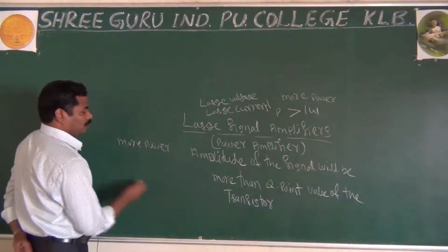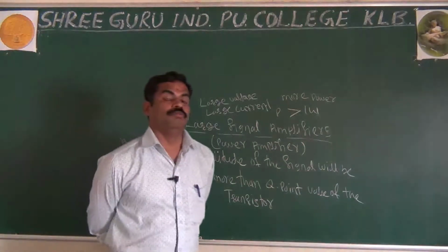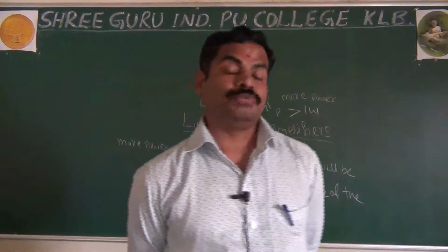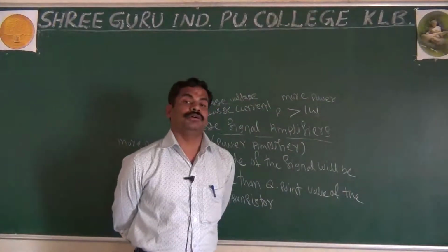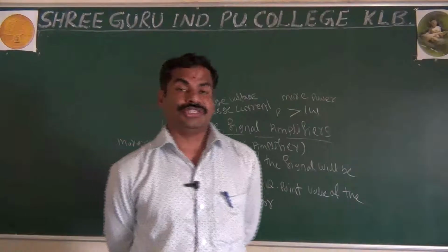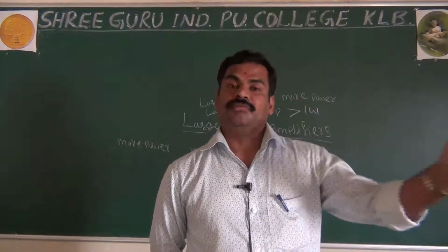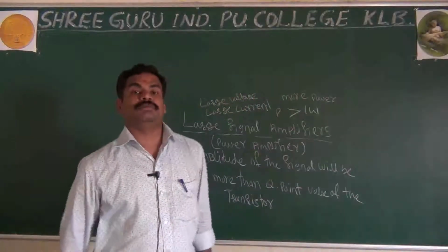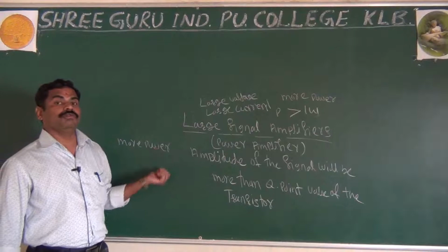and having more power dissipation. The most important thing is power efficiency. The efficiency of the power will be very high. As I said, in your small signal amplifier the efficiency is very low, but in your large signal amplifiers you have more power efficiency.